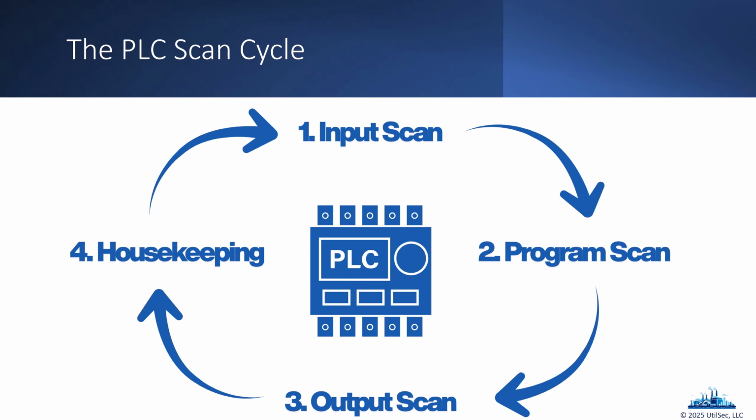Just keep in the back of your mind the PLC scan cycle, bringing in the data, running the logic. Now what if we've manipulated that logic, which then, remember, could be used to manipulate the outputs, which is what we use to control the equipment and the process in the real world. So it's all about what we are doing in the program to ultimately have that impact in the real world. Are we sending new commands, essentially, signals through the outputs?